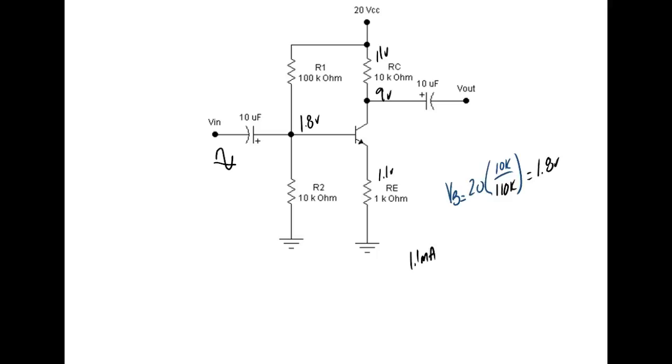All I got to do is make sure that in stereo, if I shift my left by 180 degrees, I got to shift my right channel by 180 degrees. If I don't shift them, then the two channels would be out of phase. We don't want the two channels to be out of phase with each other. But as far as in audio, if you have a phase shift through your amplifier, that's no big deal as long as it's the same in both your left and right channels, right? I just made my goal sitting here.